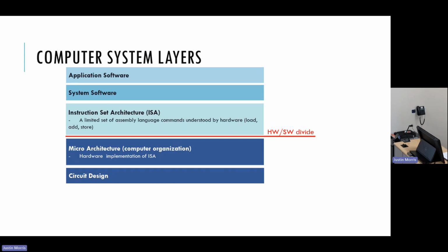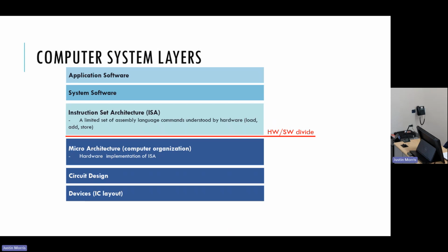And there's other things like the register file, which stores all of the data that is in the pipeline. And then if you zoom into those individual blocks, you'll see the circuit design that is inside them. So how is the multiplexer made with NAND gates and NOR gates? How is the register file built with those flip-flops and all of that? How is the ALU designed? That's where the circuit design is.